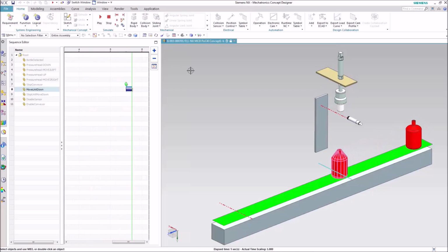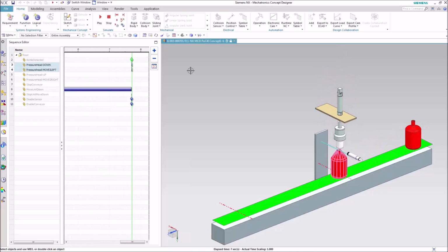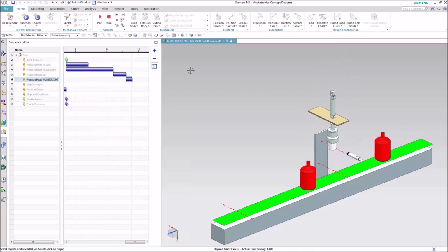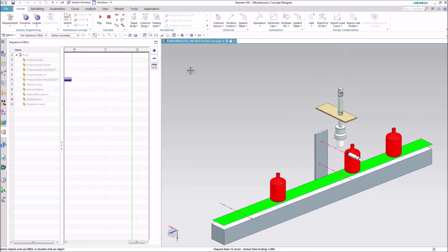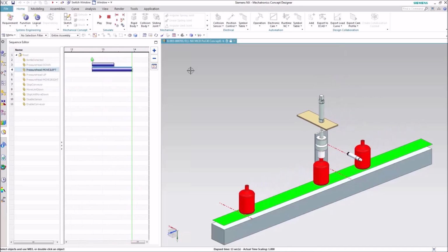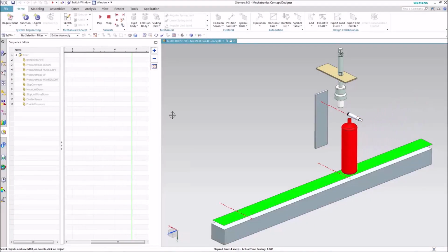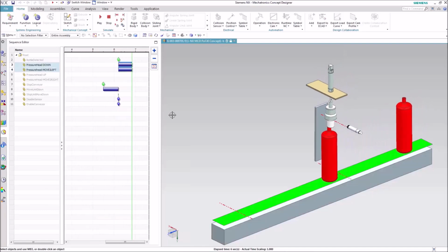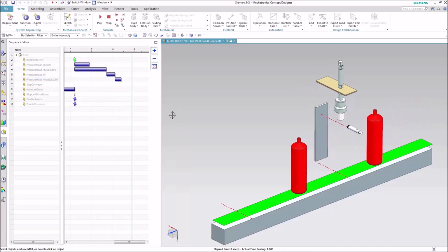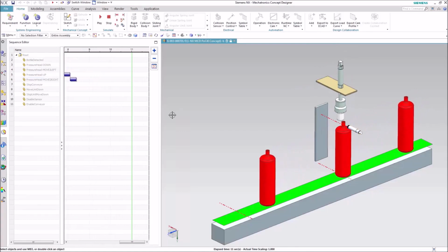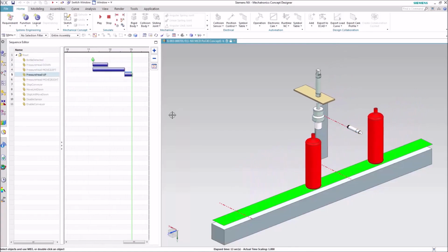With mechanics and automation, by utilizing the digital twin model, you can simulate and iterate your first concepts to reduce issues in the actual machine. The simulation worked for the small bottles, but let's now also check a taller bottle. It does work, but the stopping and starting of the conveyor must be further improved to include a soft stop-start, as the taller bottle was unstable.